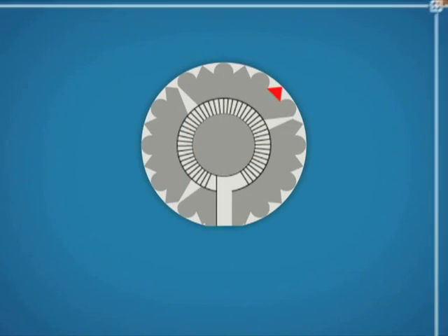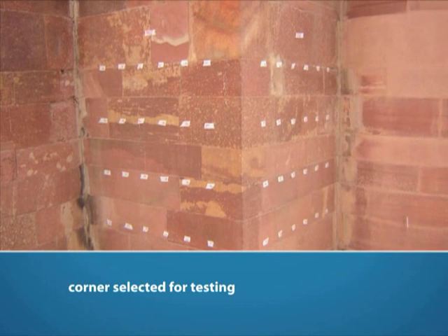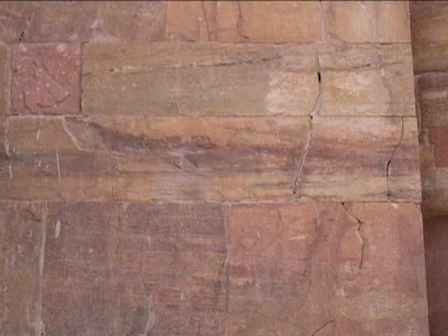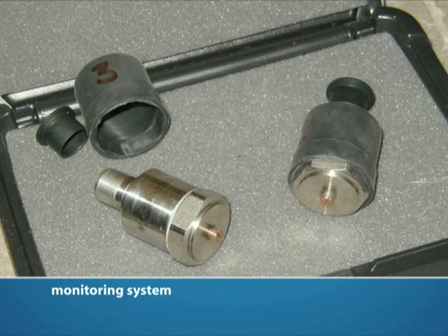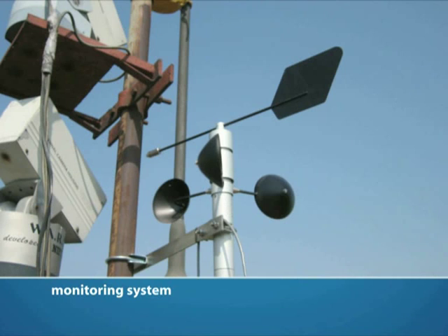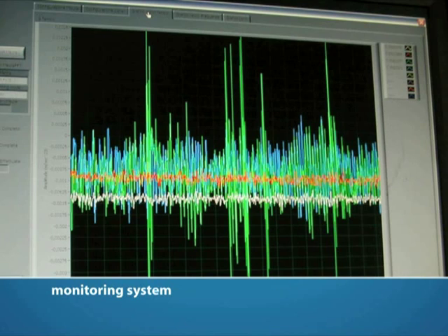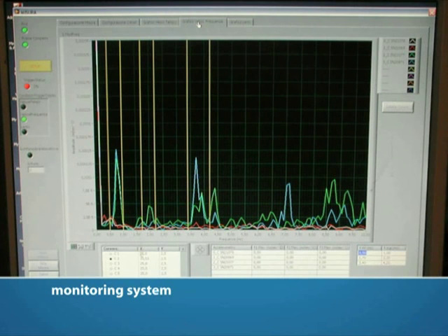Results from sonic tests carried out on a corner at the base of the tower qualitatively defined a masonry with fair compaction characteristics. Finally, a monitoring system designed specifically for the tower was installed, with the aim of characterising the response of the structure to the seismic activity. The system starts to record the data when the signal exceeds a predefined threshold based on local vibration conditions.